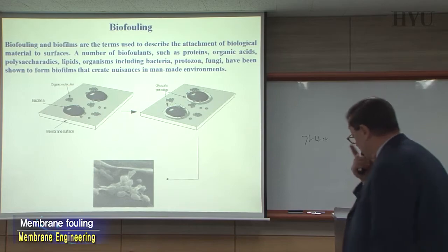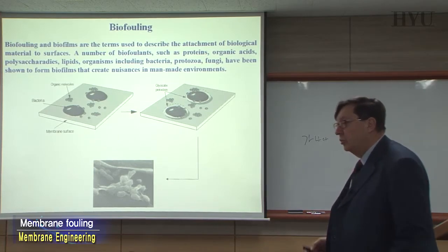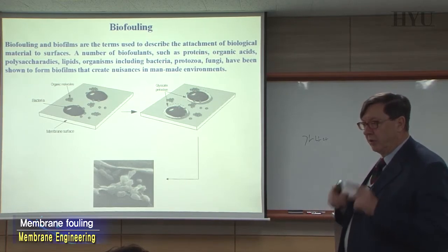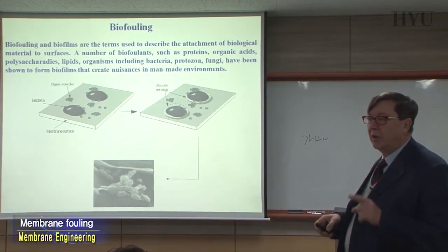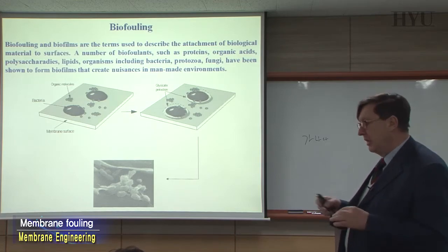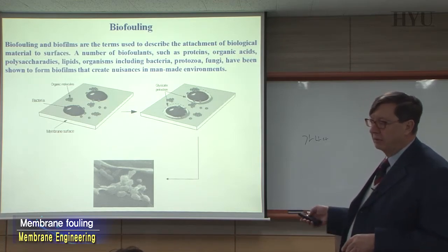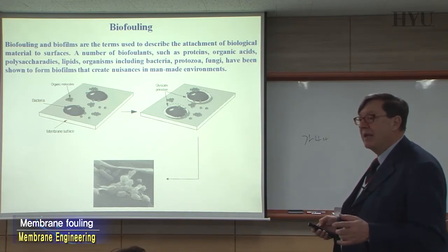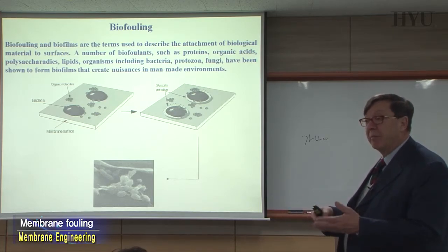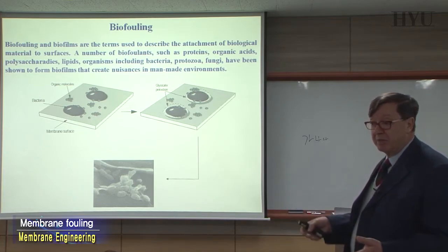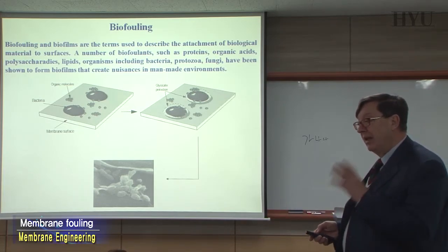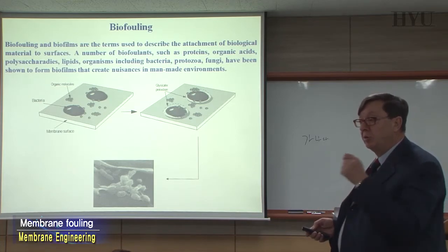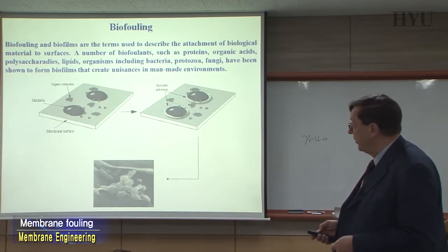Something about biofouling. Fouling, I told you today, if you're not able to control fouling, you are not a good membrane engineer. In any situation, with protein, with antibiotics, with salts, with amino acids, you must be able, eventually through pilot testing and some experiments, to identify the level of irreversible fouling, to operate in situations in which you don't induce too much fouling, etc.